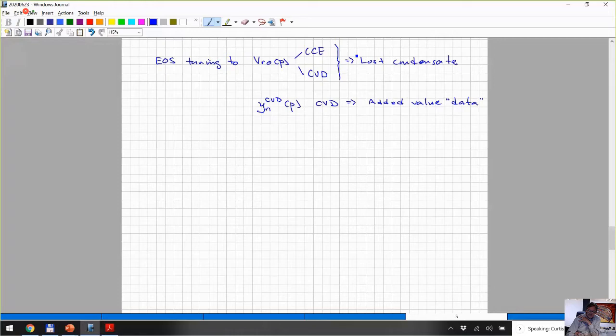And the magnitude of how much that is, because I mentioned it yesterday, no matter how much it is, if it's 20 or 25% or 15%, that oil is not going to be mobile. So it doesn't matter getting the actual volume right. And for leaner condensates, it's difficult for the lab to measure such small oil volumes accurately. So the fact that this is an immobile saturation means the magnitude is not important.